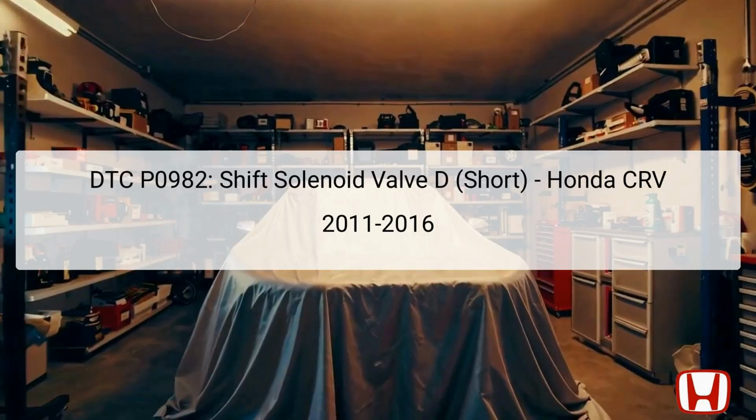The DTC P0982 indicates a problem related to the Shift Solenoid Valve D in the Honda CRV model years 2011 to 2016. This error arises due to a short circuit issue in the electrical circuit of the solenoid valve, rather than any mechanical issues within the transmission itself.